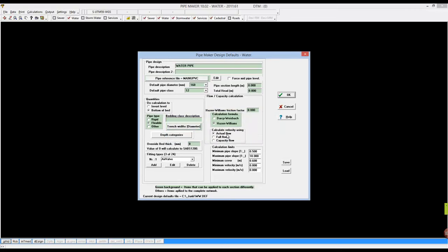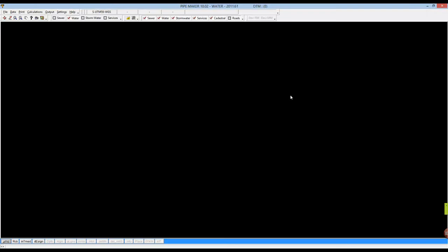It's just moaning about the friction factor. So this is Hazen and Williams. I would probably use something like 140. If you go to the help file here, there are prescribed friction values. 140 would be sort of a medium pace friction for new and used pipes, so it's quite a nice friction value to use there. Alright, so let's go back to Model Maker.